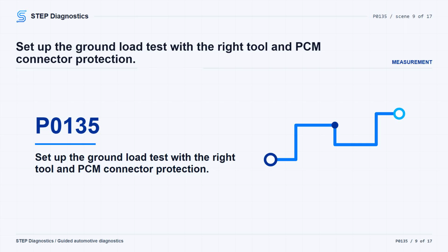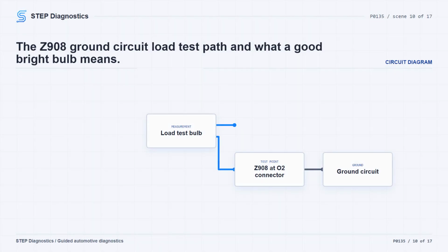Use the GPEC Diagnostic Adapter 10436. A 3156 bulb has approximately 6.0 ohms of resistance when the bulb is powered and draws approximately 2.0 amps of current. A 12-volt test light can be substituted only if it draws enough current to effectively load test the circuit. Many high-impedance test lights draw very little amperage, less than 0.1 amps, and are not reliable to load test a circuit. To perform a proper load test, the tool should draw more than approximately 0.75 amps.